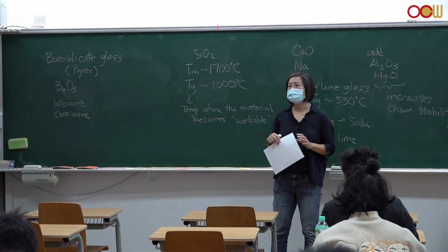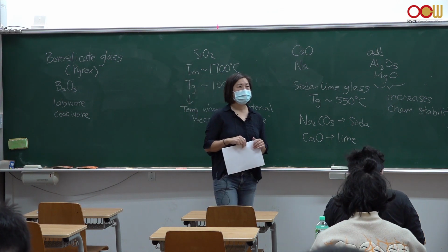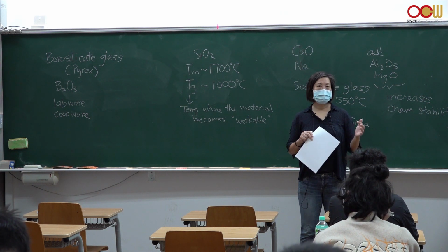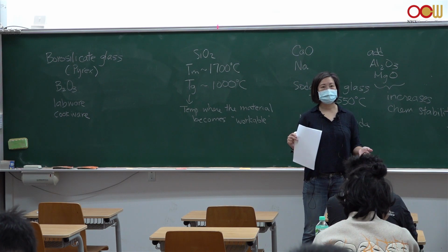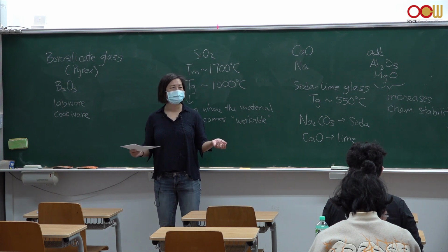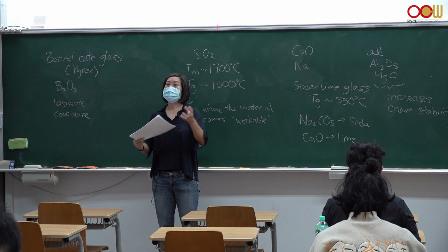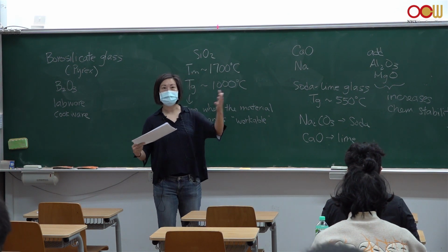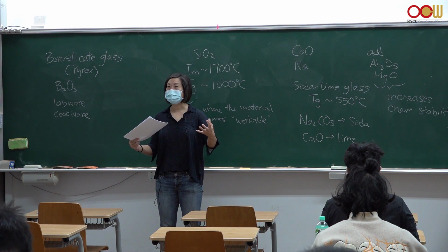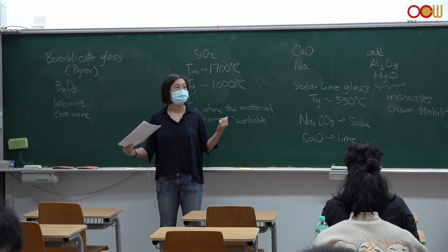So Corning is a glass manufacturing company. I mean, they do a lot of other things, but they're very well known for manufacturing glass. And they developed the first really heat-resistant glass ceramic material. And some of their materials, it's quite smart, the way they worked on it, because when you heat something, the bonds expand, right? It's really difficult to prevent something from expansion because you're adding energy with heat, the molecules are vibrating, and so the bond length is going to elongate.